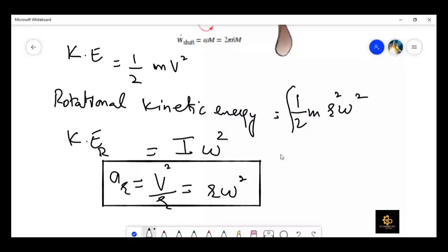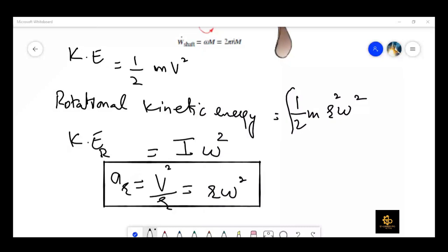Now in many engineering applications, there is a rotational effect, like turbomachinery. In this, we usually have to take the moment of the linear momentum of the flow stream, and we also need to cater for the rotational effects which are caused by the movement of the linear motion. So how do we calculate the moment of a linear momentum? That is quite simple. Let me show you the diagram first, and then I will explain it from there.